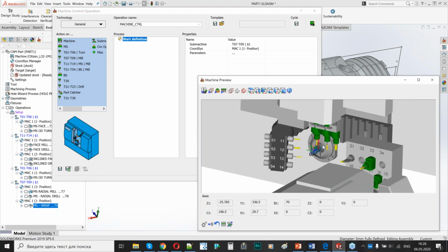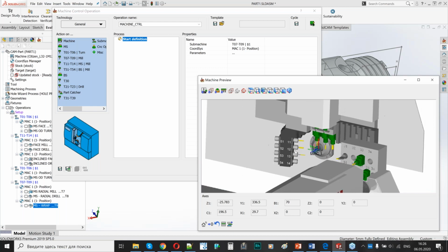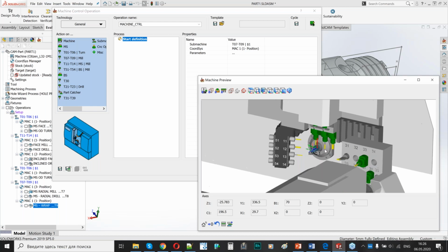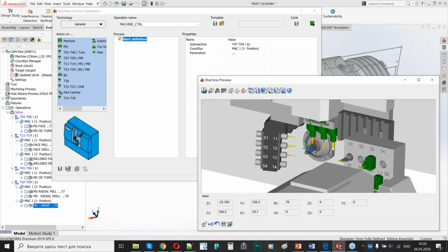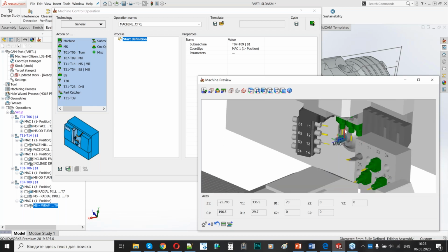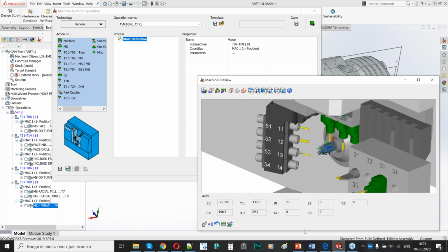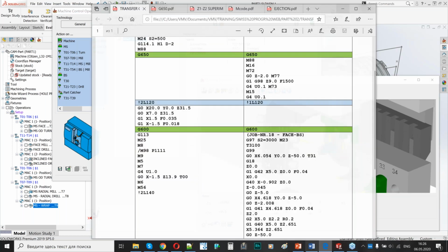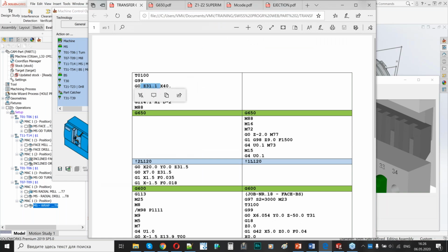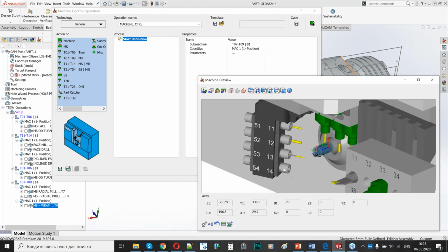So before the part transfer and cutoff, I would like, for example, to move this gang to its home reference in X direction, Y direction, and to retract the B axis to its 0 position. I would like to clean this space to see what is going on and to prevent some gouges during the part movement, because as you remember, our plan is to move the part out of the spindle to perform the cutoff process. So I would like to make it safe.